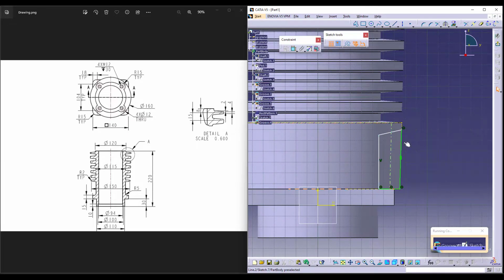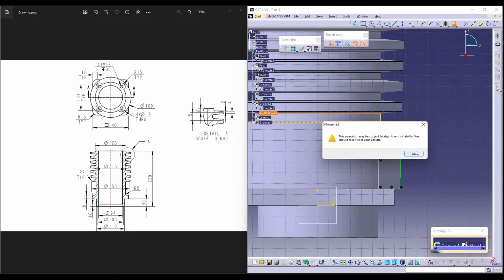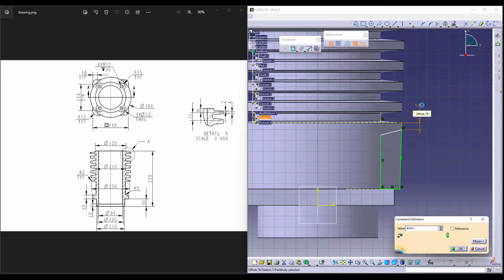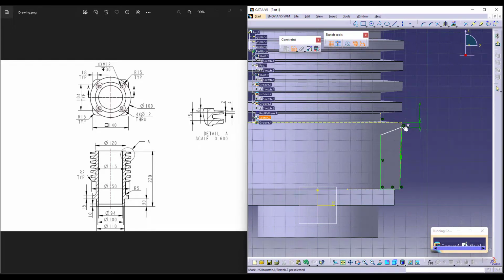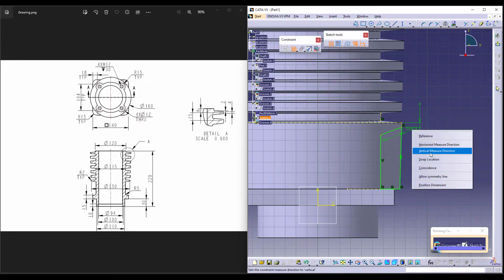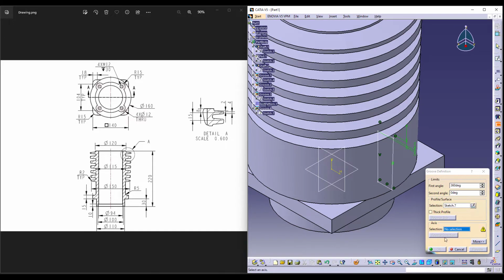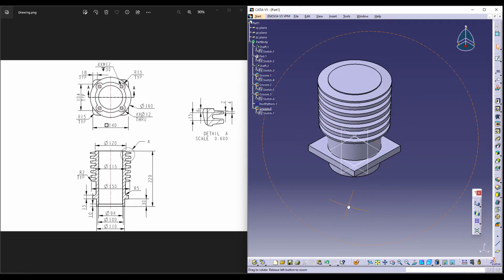Now, this is supposed to be 115, even this is 115, so I'll use that as the reference and then keep them in line with each other, which is actually a better option. And then the overall distance from here to this end point is similar to what we have done, which is 4, and the distance from here to here is actually supposed to be 2. I'm trying to remove this with respect to the center axis. I already have an axis, so I'm selecting the axis. This is your internal cut.